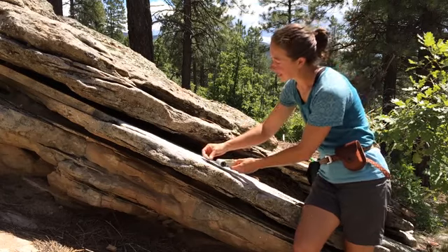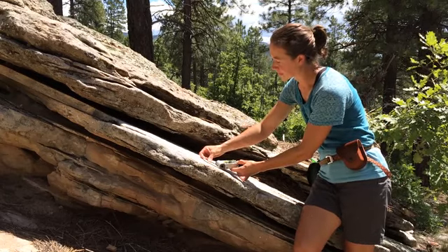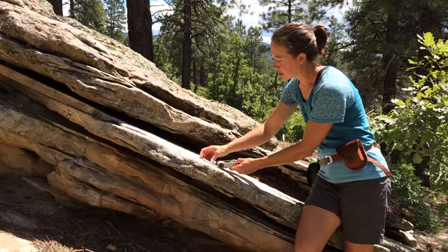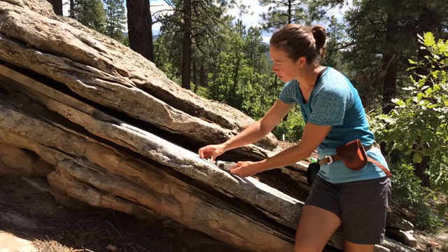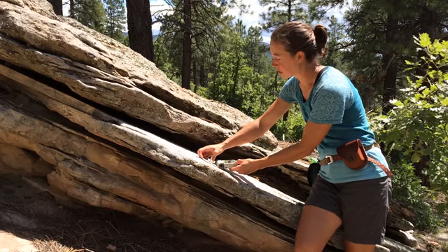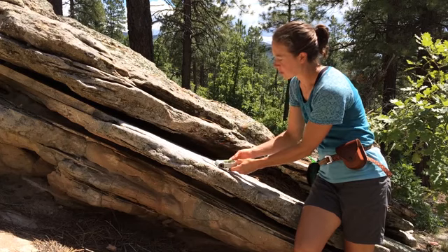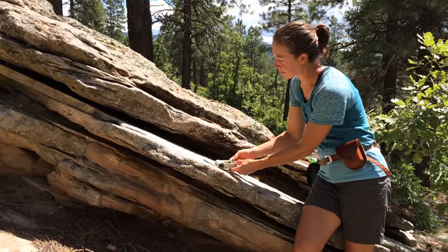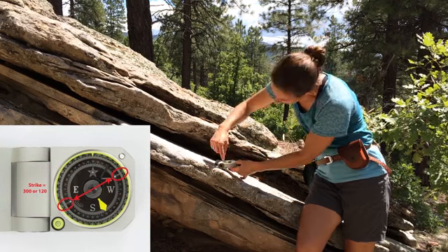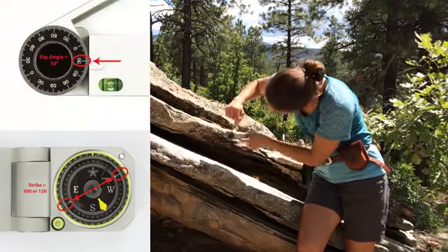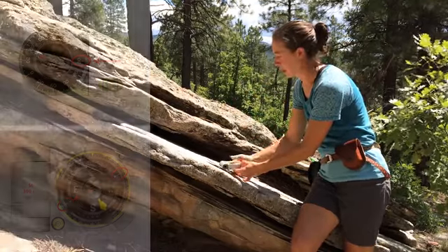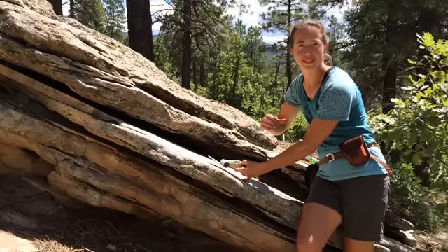The first step is to place the lid against the plane. Next, level the compass face by swiveling the lid and also rotating around the major axis. When the compass is level, press and release the needle button. Read strike off of either end of the magnetic needle. Read dip off of the hinge dial, in this case where it meets the top of the dip indicator, and then take note of dip direction.